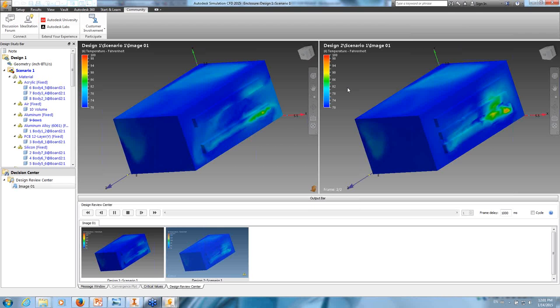So that is why ADV5 is considered more stable, more numerically accurate, and things like that. Sometimes, for some models, it is considered less stable. So if you were to do like a free surface simulation, we would actually say use advection 1. So there's still some things that are working their way out.